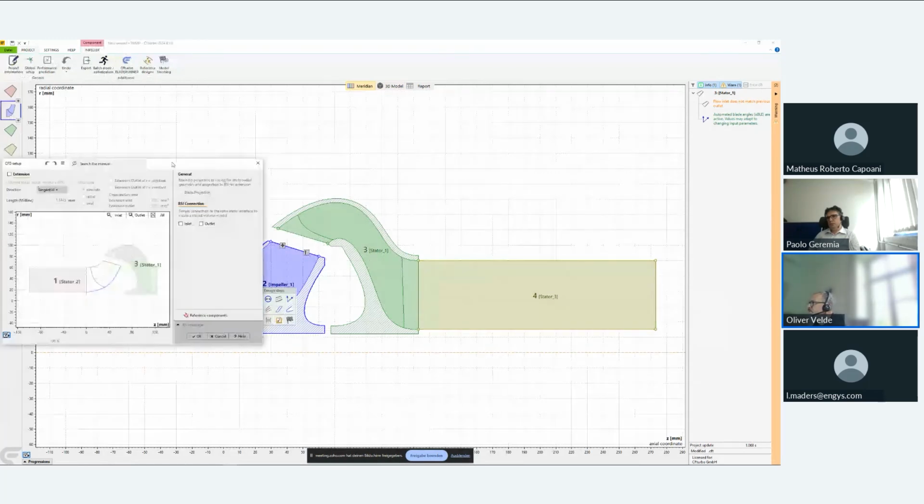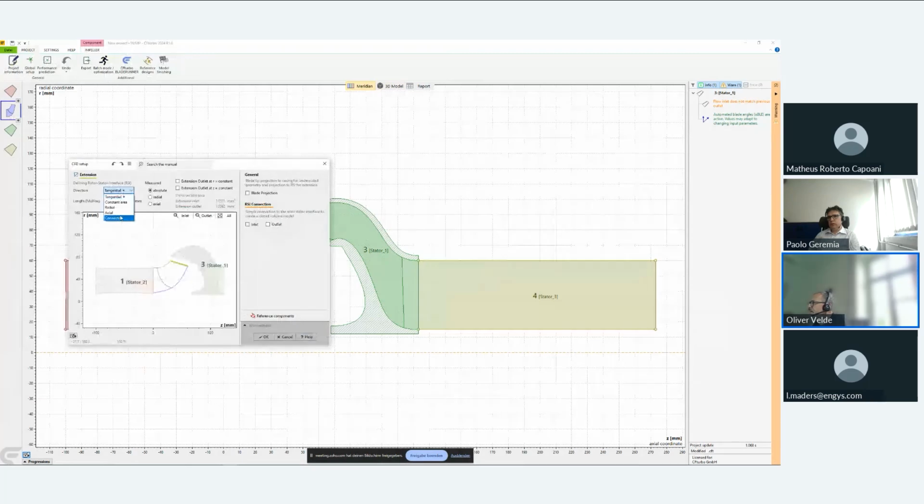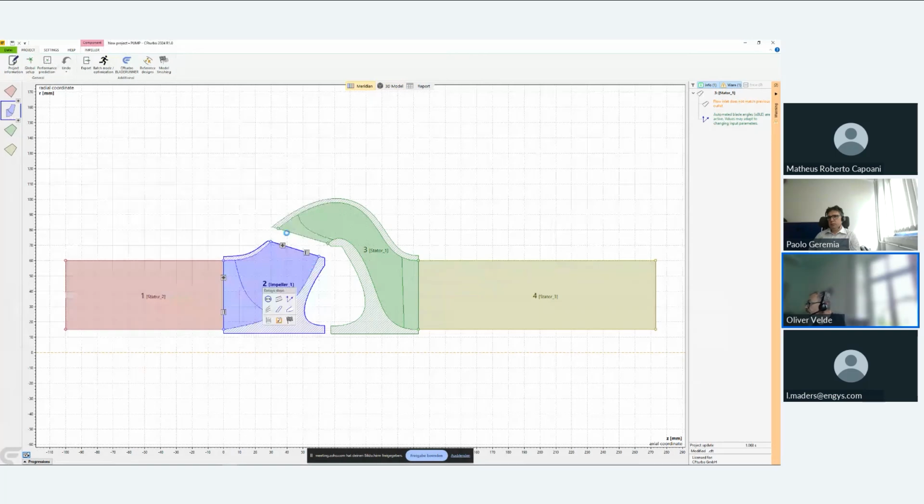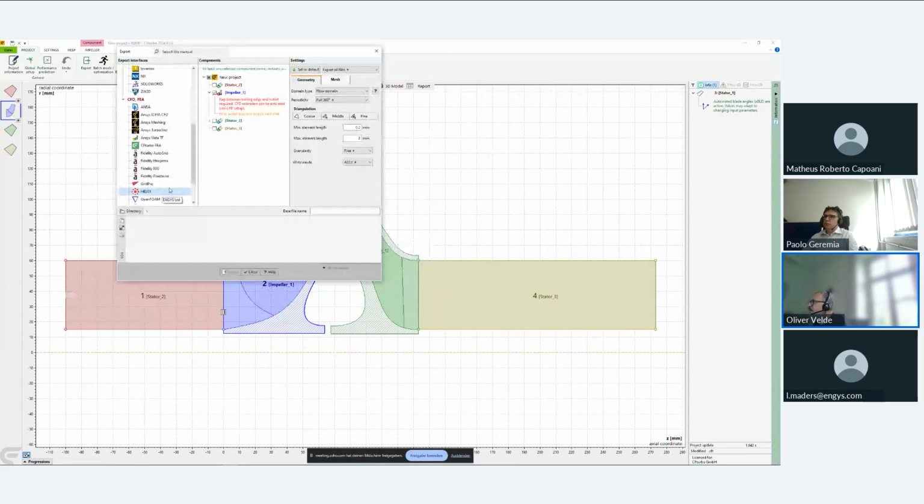And here I can just introduce a kind of virtual domain, and it will just close that, and then the whole model is watertight, and I can go to the export panel and choose Helix, for instance, choose the virtual flow domain for the export, choose all the components I want to include in the export, and then tell whether I want to export all necessary files or only the config files, which I'm going to do here, because otherwise it would generate STL files, which again would take a couple of seconds.